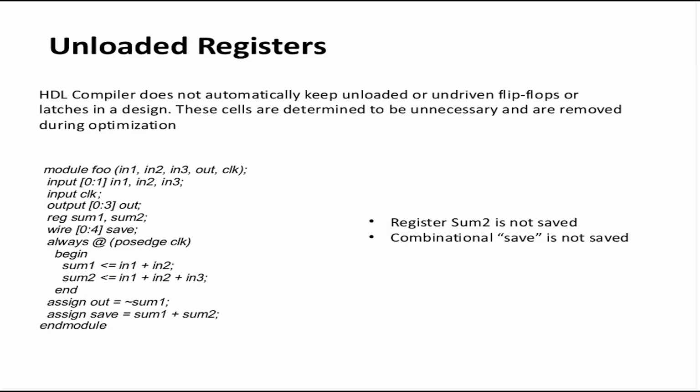This is a particular case of unloaded registers. The synthesis compiler will not automatically keep unloaded registers or undriven flip-flops or latches in the design. At the start itself, the compiler knows these are not necessary, and they are removed even before the design is completely optimized. So they are removed in the first pass of optimization. What are unloaded registers? What are undriven flip-flops?